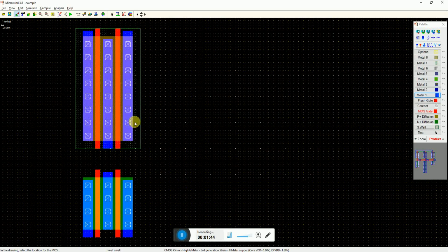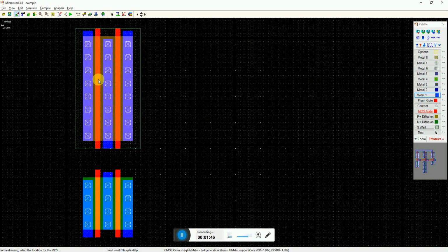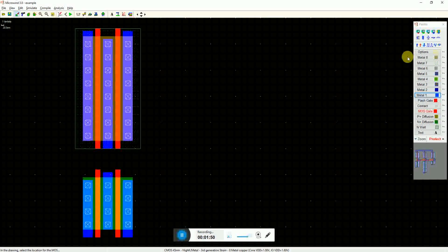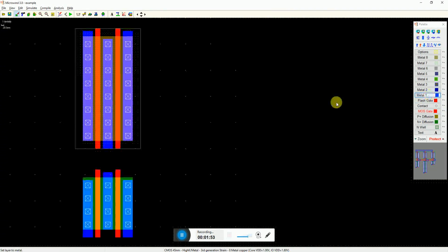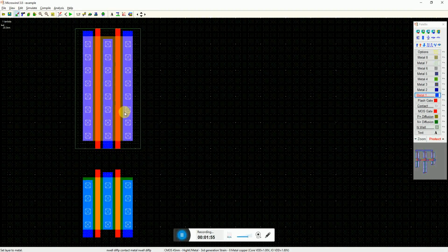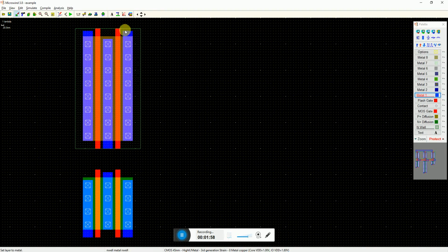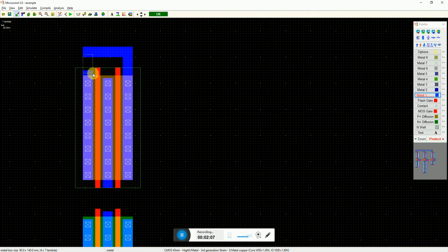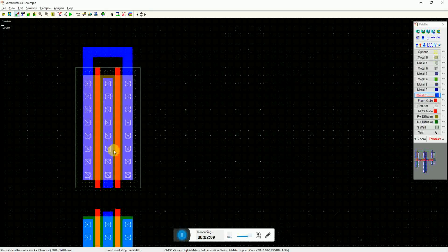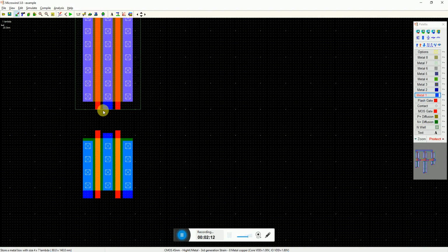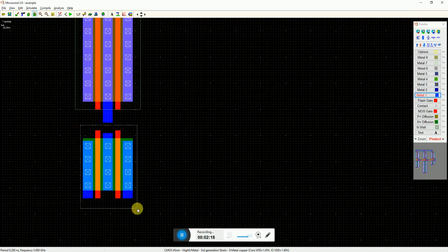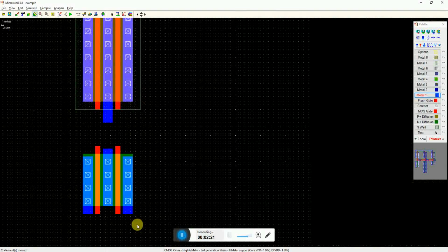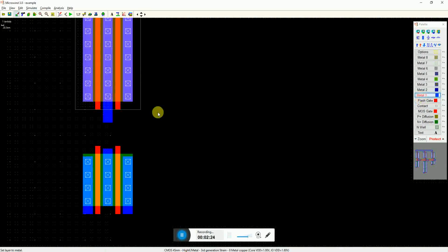So here there are two PMOS transistors connected side by side, and I just make the formalities. I take the metal one. The transistors are already in parallel, but if I take these nodes above and make a horizontal loop connecting them, that will be the entry node and this will be the exit node, so the transistors become parallel. I bring it down and shift the NMOS a little bit down to make spacing, and this will be my output node.